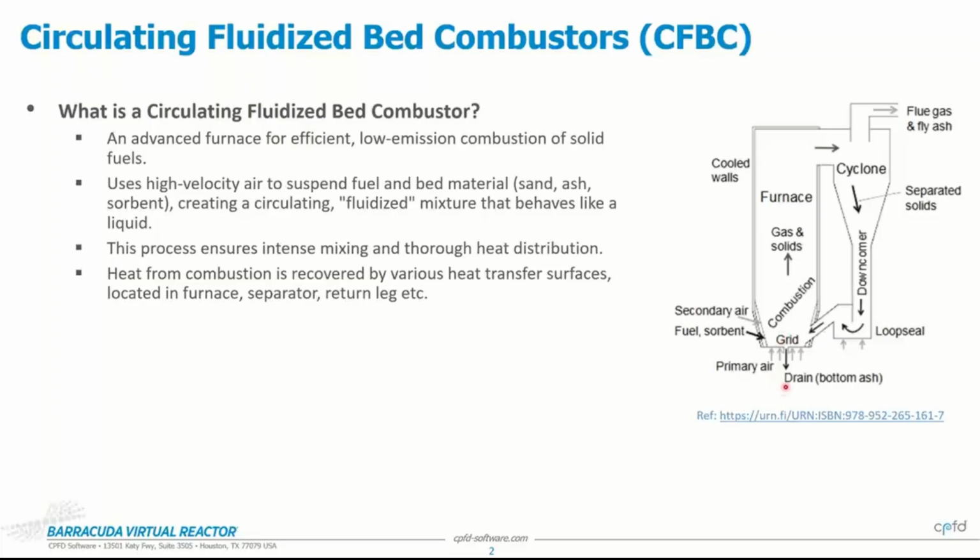Then you have basically primary air coming in from the bottom of the reactor. Now, this air serves two purposes, right? One is it fluidizes the solids. When we say fluidized, for those who are not familiar, what we're talking about is the solids almost start behaving like a fluid, essentially. The motion of them.